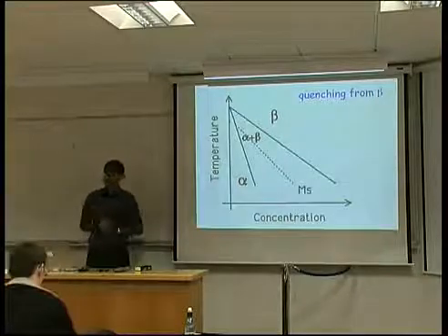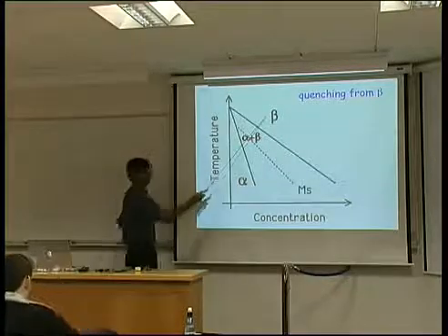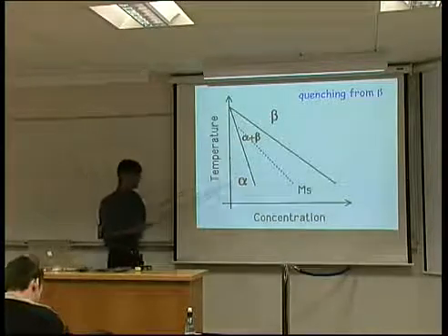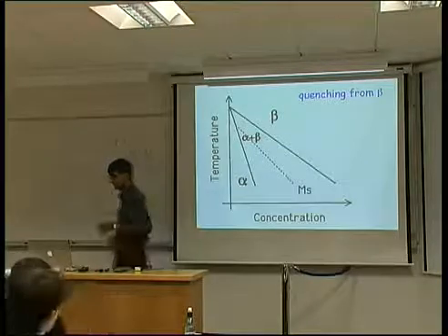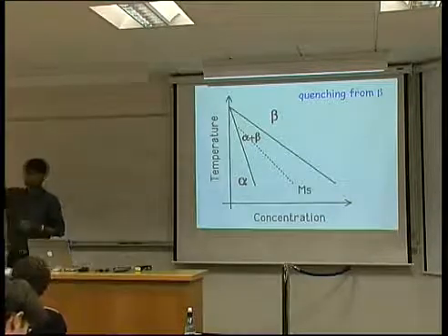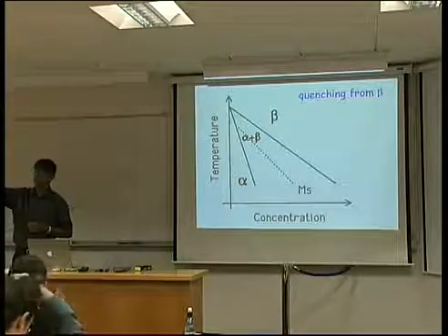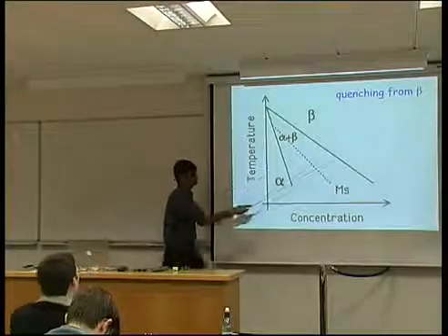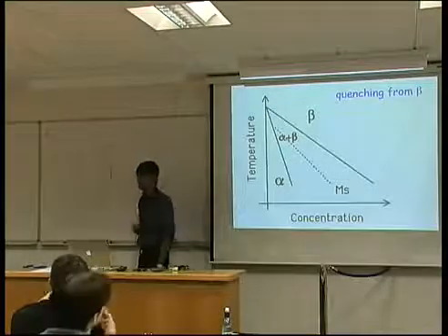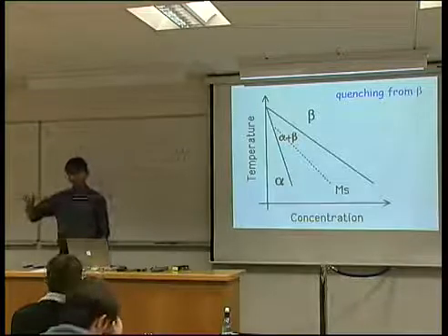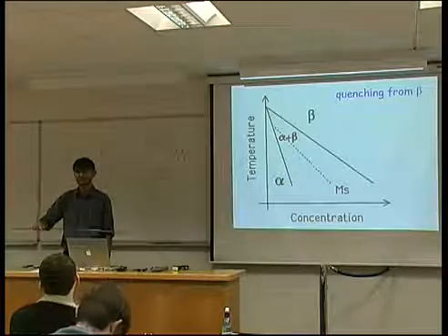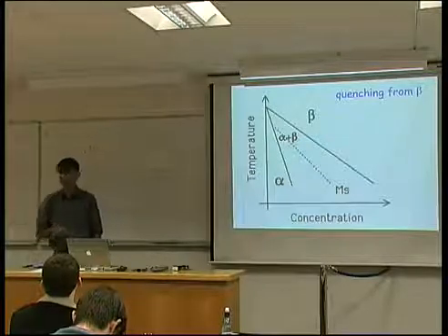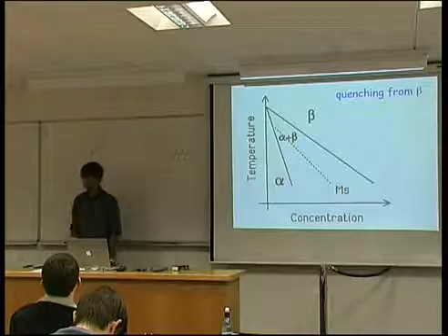Okay, we have the beta phase stable at high temperatures, which is body-centered cubic, and the alpha phase, which is hexagonal close packed. And of course, if I cool slowly from the beta phase field, I can precipitate alpha, and that will involve the diffusion of elements, because look, the alpha and beta have different equilibrium compositions. But I could also cool extremely rapidly, and then what do you expect will happen? Martensitic transformation, because Martensitic transformation does not require diffusion.